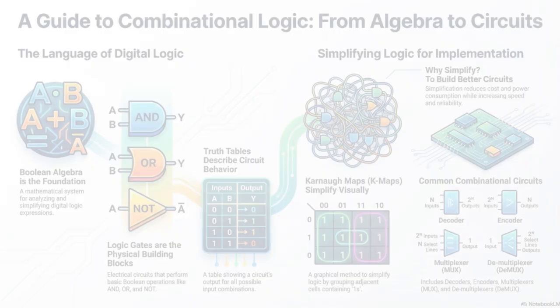And that's a total game changer because you can then build a circuit using whichever gate is cheapest or most available. For example, the sources gave that simple expression: x plus x bar y. You apply some basic Boolean laws, and it just simplifies down to x plus y. That one algebraic step could eliminate multiple gates from your design instantly.